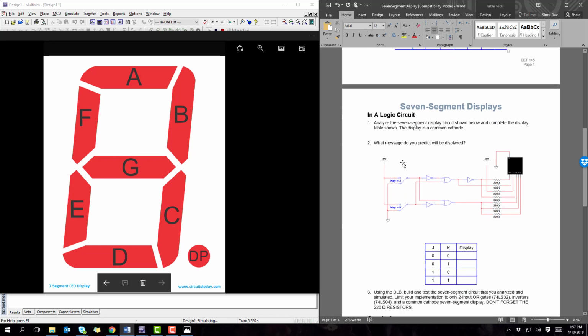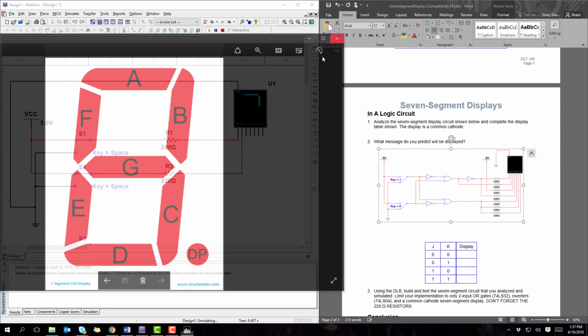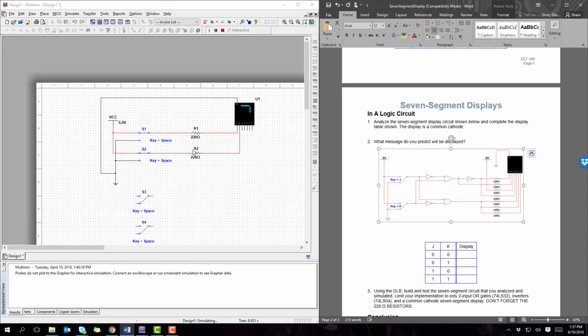Okay, the next part of the worksheet is you'll have to make this circuit on Multisim. So you can delete this completely and recreate it, or you can delete just this part of it right here. But you'll need to make this segment right here. You guys should know how to make these. We've been making AOI circuits the entire class period. You'll need 3 NOT gates and 2 OR gates, it looks like. Okay, and you're just going to wire it up just like it is here.